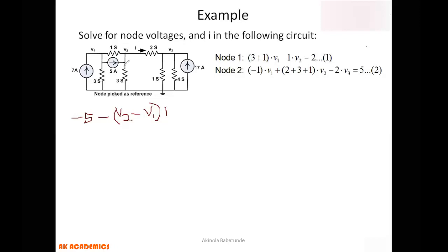All right. Also, we have dealt with everything coming in from this angle. Now let's deal with everything from this other side here. For V2 with respect to 3s. Okay. So what do we have? This is 0, isn't it? The voltage here will be 0. So we have plus V2 minus 0, all multiplied by 3. And then we go on. What about what is happening to 2s here? The current passing through 2s from V2 to V3 becomes plus V2 minus V3 multiplied by what? By 2.